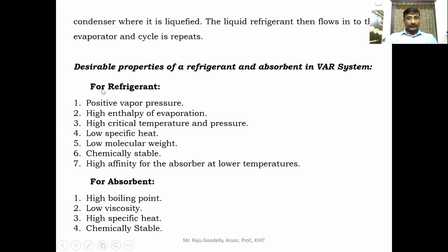So for a good refrigerant, positive vapor pressure is required. Positive vapor pressure means the pressure in the evaporator must be above atmospheric pressure. Positive vapor pressure is required to avoid the leakage from the evaporator to the atmosphere.